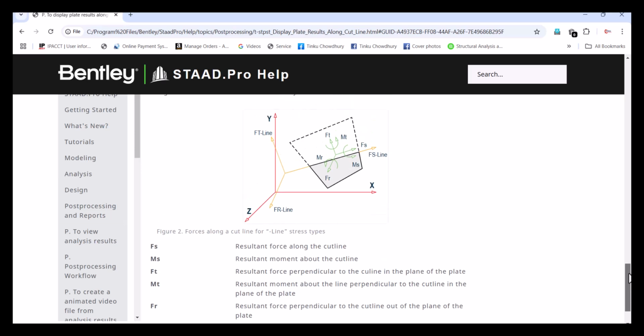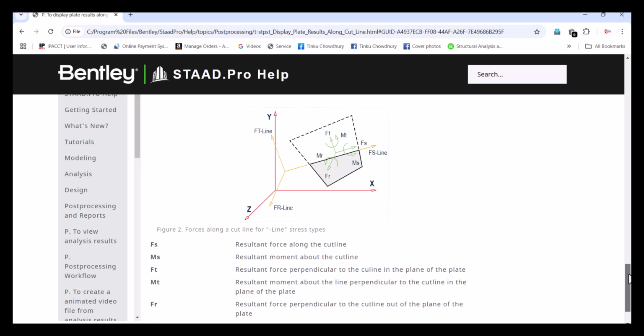So again, there is also another table on its right that is for the force. That means, very simply, all the individual stresses are multiplied with the respective length of those individual elements, and they are added together to find the total forces. Okay, so we are converting from the stress to the force.